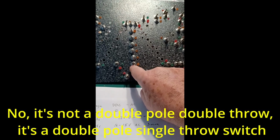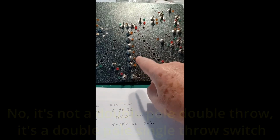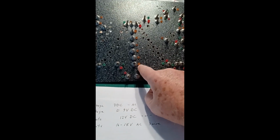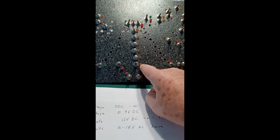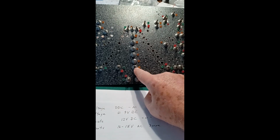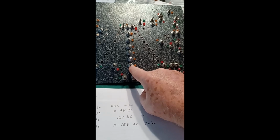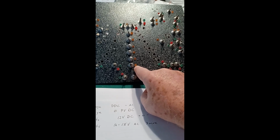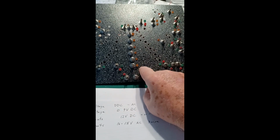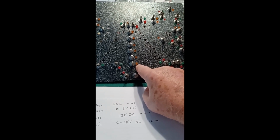So I can use one side of the switch to run back to the track, telling it to energize that block section, and then I can use the other side of the switch to run 9 volts to my LED, so that when I turn that switch on, it sends power to that particular block section, and at the same time, it sends 9 volts to the LED, lighting the LED. I turn the switch off, and it shuts off the power to the track and turns off the LED.